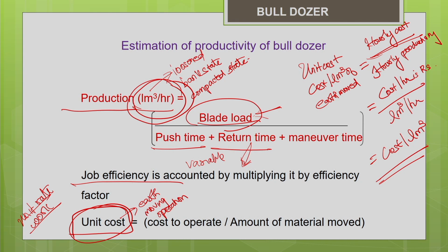This is the data which we will be commonly using. This will be a part of what you quote in your bid. The unit cost of production of this activity forms a part of the unit cost you generally quote in your unit rate contract bidding. That is why the estimation of this is very important, and you should estimate it as accurately as possible, so that you can properly plan for your bidding.